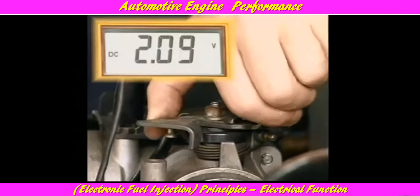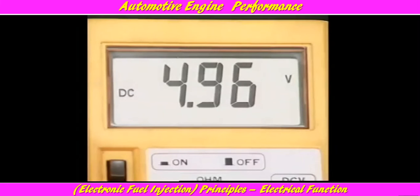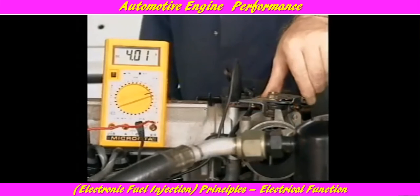Although most injectors operate at the nominal battery voltage of 12 volts, many sensors have a reference voltage of 5 volts. This is done by a voltage regulator in the control unit. It gives more accurate signaling, as fluctuations due to changes in battery voltage do not occur.